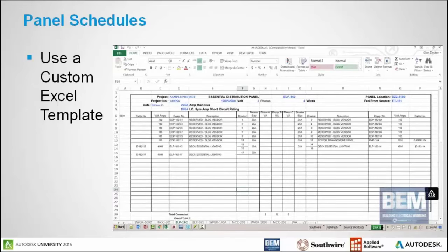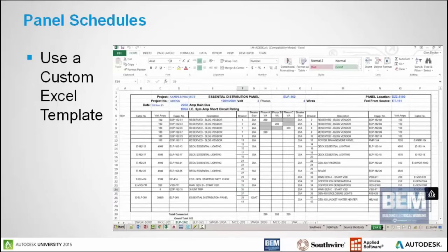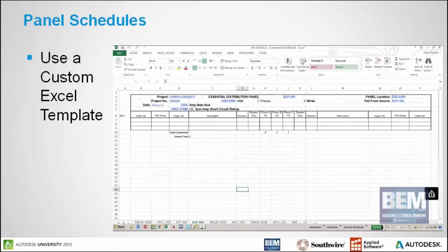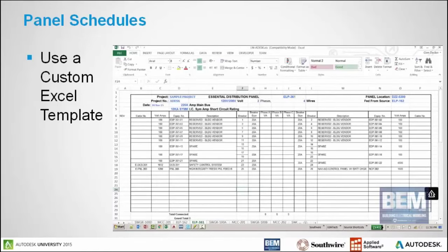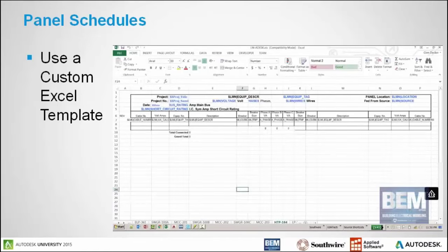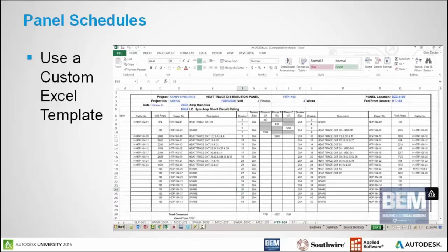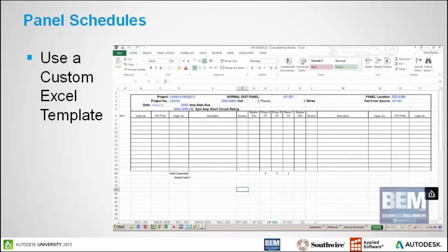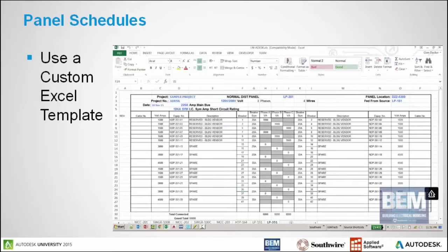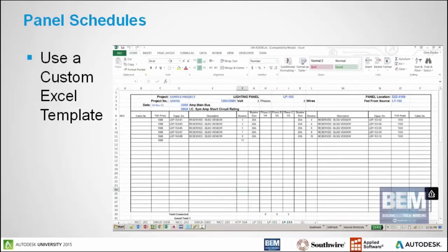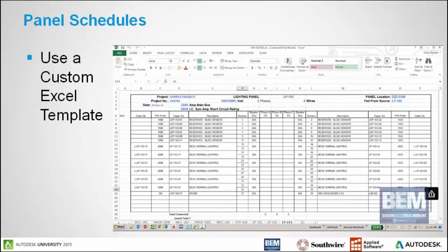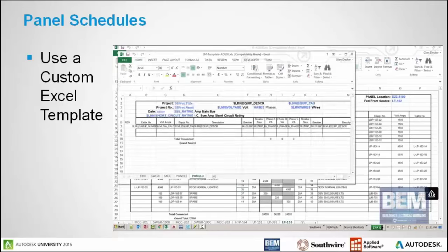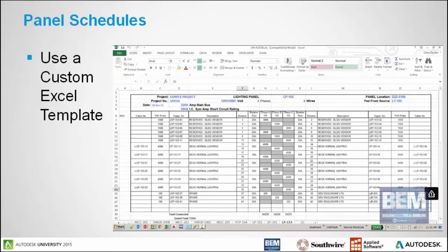You can also do panel schedules. By assigning the circuit designation in the database and the load, the program will size the breaker and will help us to create our panel schedules. This will work with single-phase or three-phase panels, and it will work with any voltage level, really. I've done 120/208 three-phase, 240, also done 480 volt panels and 277 volt lighting panels.